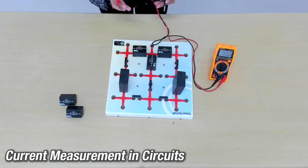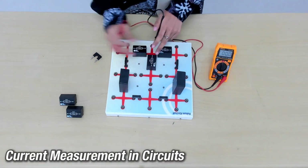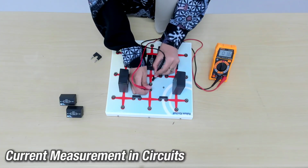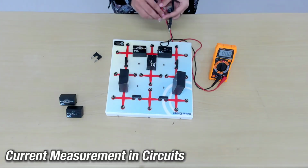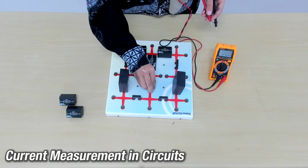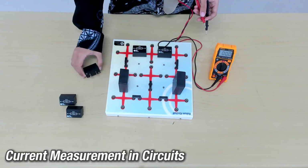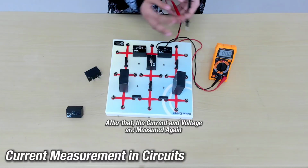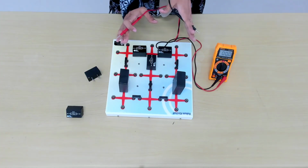Okay, and lastly, measure the current of I3, which is located in the middle part of the circuit. Unplug the connector first and then measure the current. And don't forget to record the reading. And lastly, we also use the second resistor variation, in which R3 is replaced with R4, and the voltage and current values are measured again using the same method as in the R3 variation.